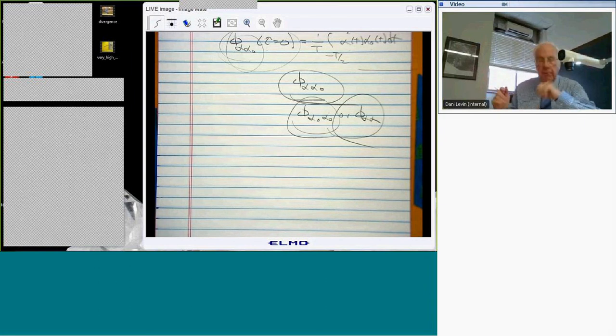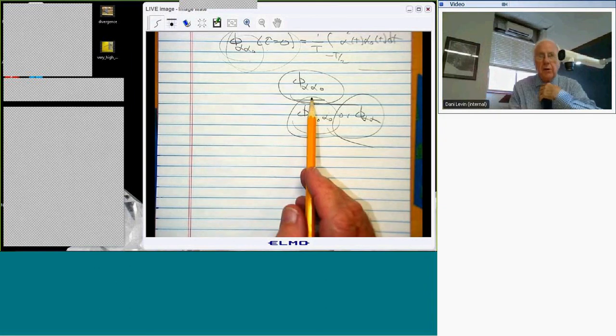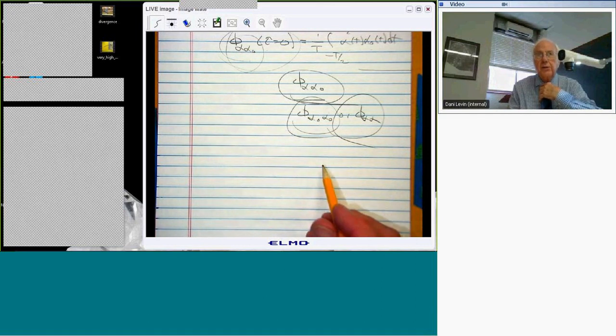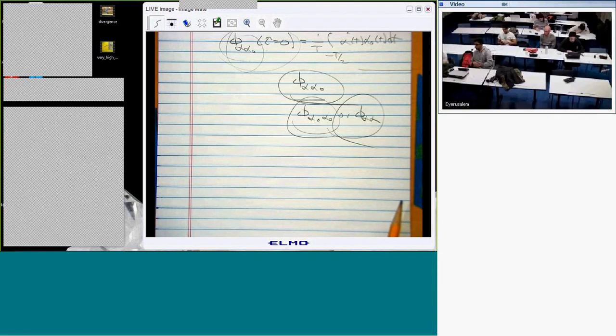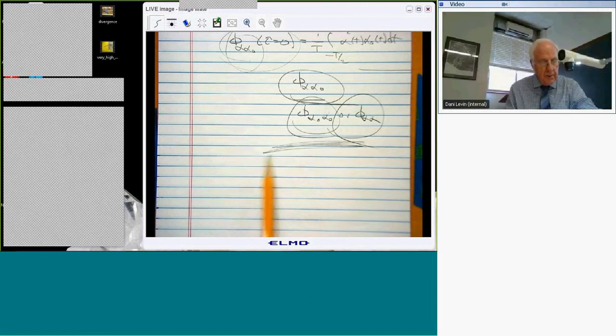Then by looking at the cross correlation and comparing it to the size of the autocorrelations, you could get some sense about how important the correlation is between those two signals. Does that help? Thank you. You're welcome. That's a good question. I'd never thought about that, actually. But I don't give any particular significance to the cross correlation when tau equals 0, unlike the autocorrelation, where it's definitely the mean square, and that's often what you're interested in.